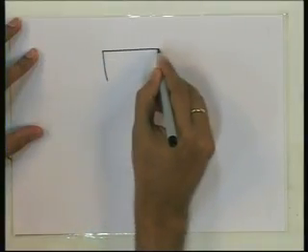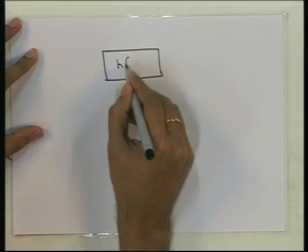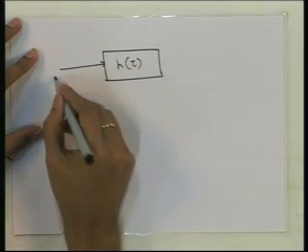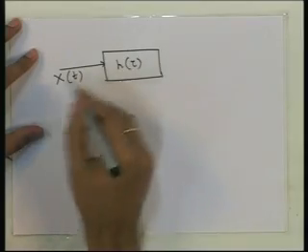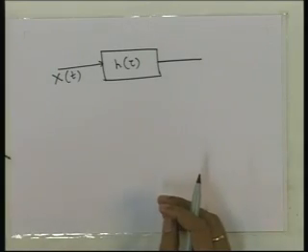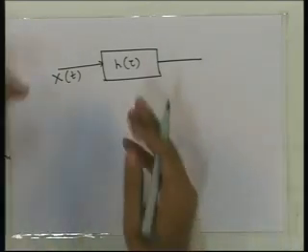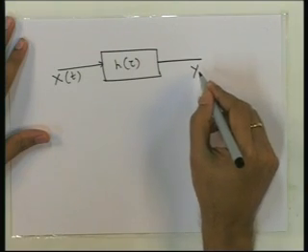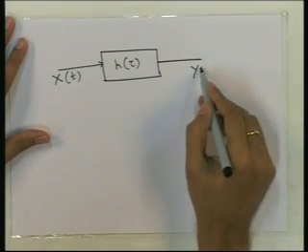Okay. Now, in this context, it is also very important to see what happens when we pass a stationary process through a linear time invariant filter. So, if you have a filter with impulse response h tau, and we pass xt, a random process, through it, say we have a microphone and a voltage is generated and we pass it through a system, a filter with impulse response h tau, what will be the power spectral density of the output process?